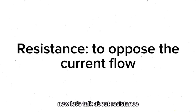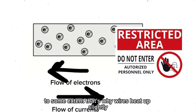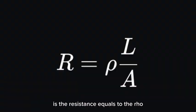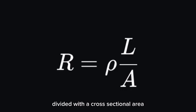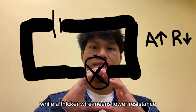Now, let's talk about resistance, the opposition to current flow. Every material resists the motion of electrons to some extent. That's why wires heat up slightly when current passes through them. The resistance of a wire is determined by R, the resistance, equals rho, the resistivity of the material, times L, the length of the wire, divided by A, the cross-sectional area. So, a longer wire means higher resistance, while a thicker wire means lower resistance.